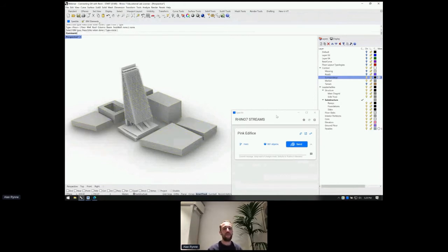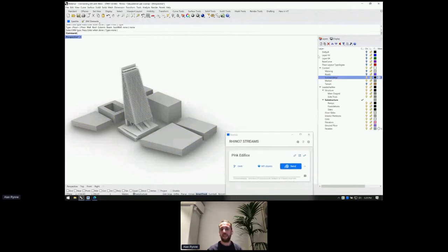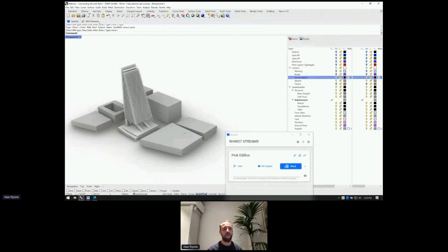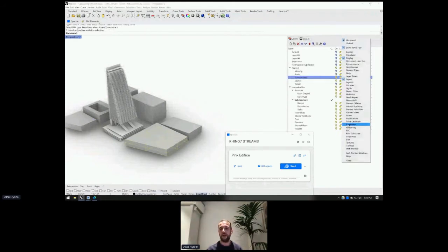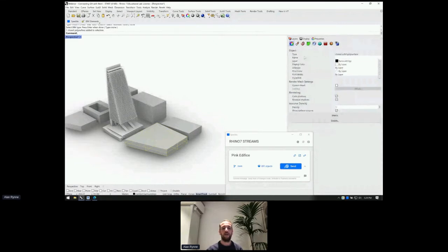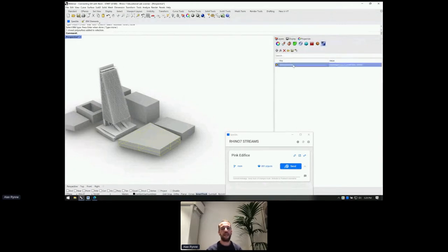So what has happened here in Rhino? What has happened is that when you run this command, let me see if I can open the properties panel. When you select that object now, if you go to its user text properties, you now have this new property called Speckle Schema that is basically telling Speckle that when this is received in any BIM environment, not only Revit, but right now it's the only one we support, it will be received as a direct shape.